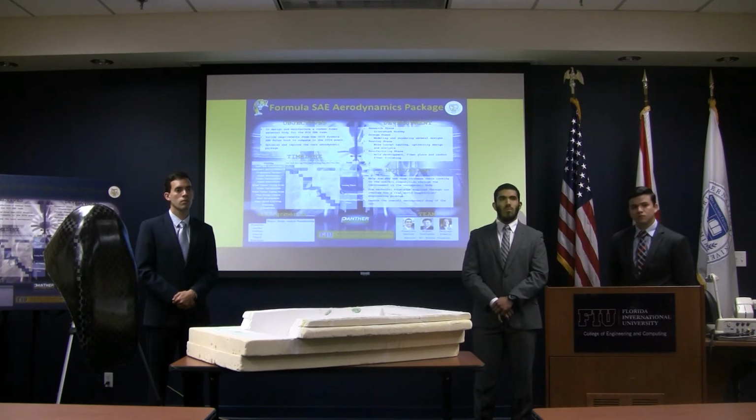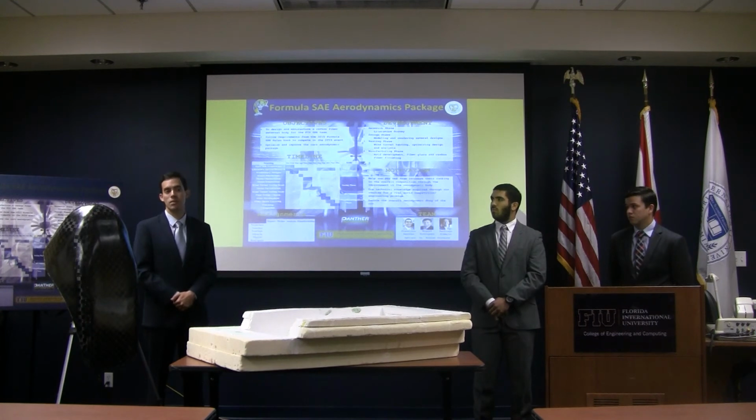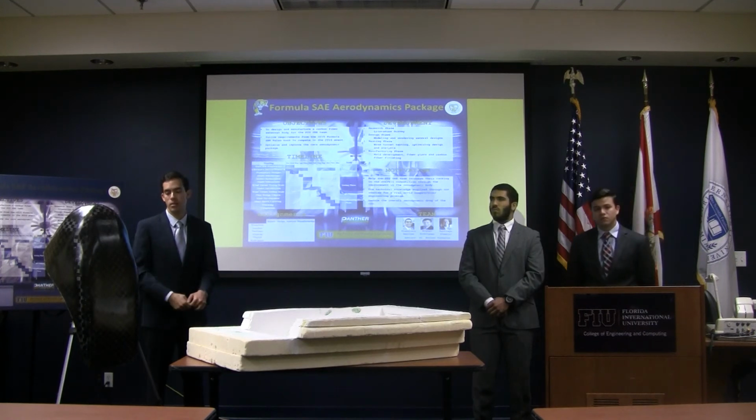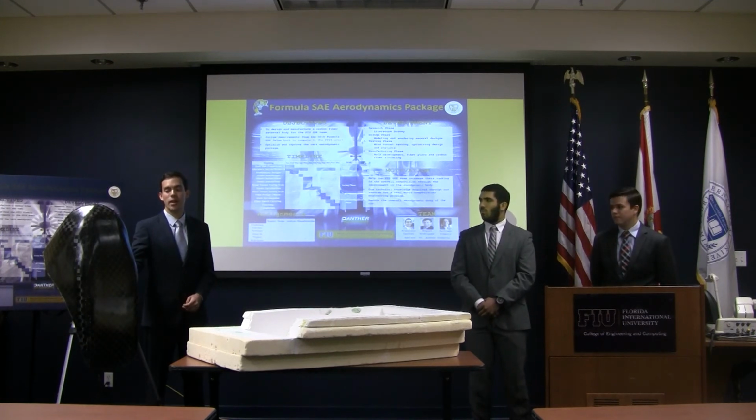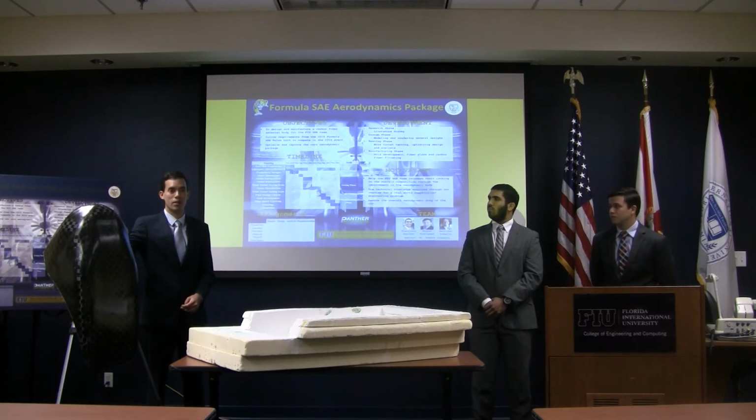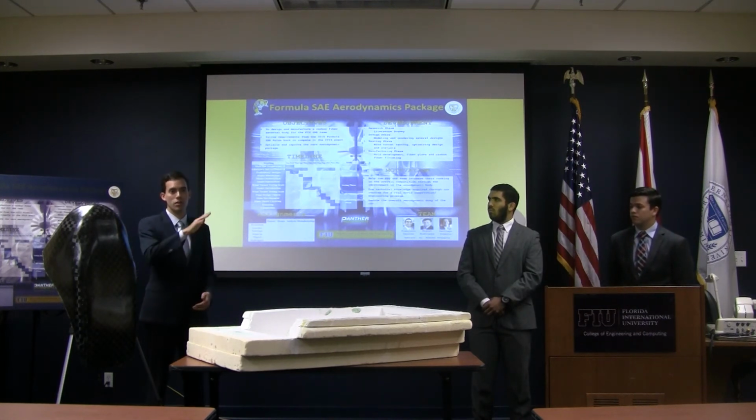Did you figure out exactly how much the whole thing's going to weigh? We didn't calculate the exact numbers, but it also depends on the number of layers that you apply on the material. The fiberglass material is, I would say, 1/3 heavier than the carbon fiber, each of the layers. So you're saying it will be 33% heavier? Around that number. You don't know the weight of that right now? No. That also has to do with the resin that's impregnated in order for the fiber to harden. Right. And we reduce the weight of that through the vacuuming process with the cotton material to absorb.